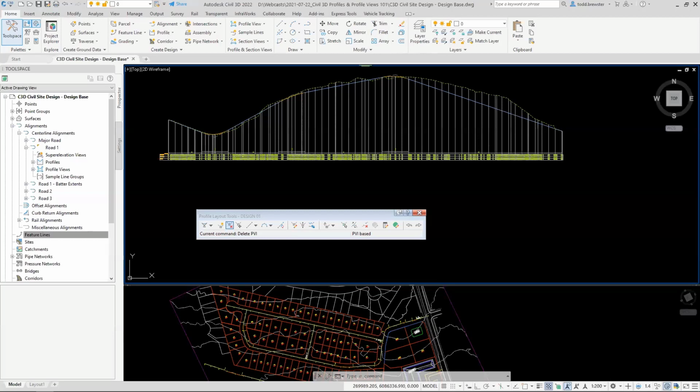The whole idea of these object types is that if you made a corridor, and then did the corridor sections, and then did the section views, and then made some edits on the profile, that would update the corridor, which would then update the corridor sections. The whole lot becomes dynamic. So it's the section views really where you'd be heading off to. In terms of presentation order, we've probably done it backwards in that we showed the section views first and then did the profiles.